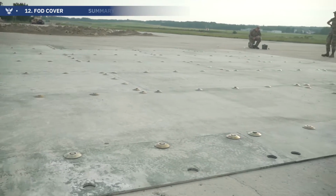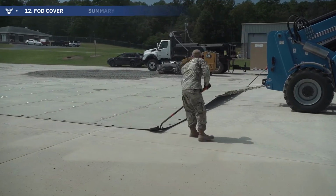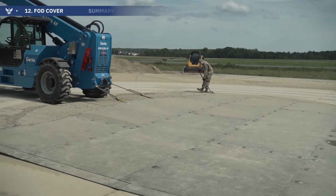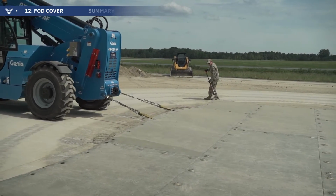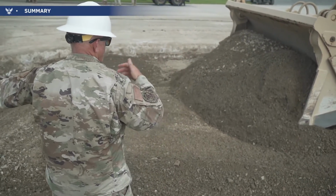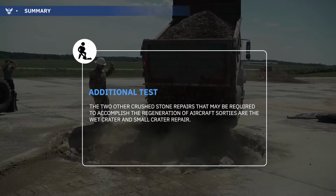This assembly can be done directly on the crater, or if adequate personnel are available, the mat can be assembled during the crater repair process and then dragged across the repair as demonstrated. This concludes the 12 steps for the crater repair procedures. The 2 other crushed stone repairs that may be required to accomplish the regeneration of aircraft sorties are the wet crater and small crater repair.